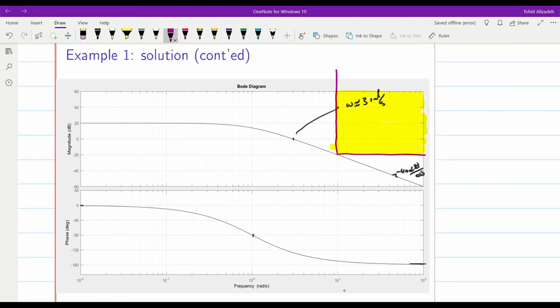For the frequencies smaller than 0.1, which is this frequency, this will be the dangerous zone for the disturbance rejection. And now we can see that the amplitude plot is just on the border. So to satisfy this requirement, we would need to move the amplitude at very low frequencies a little bit upwards at least, in order to have the desired disturbance rejection property.